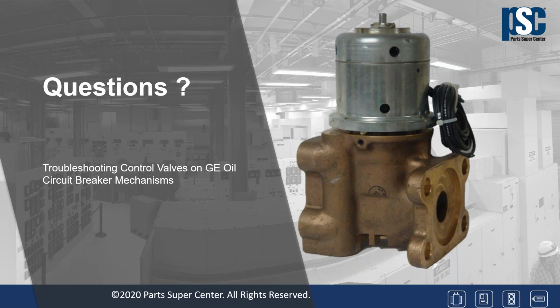So the speed at which the breaker closes is directly dependent upon the volume and flow of air, not necessarily the pressure. So it's really about flow.